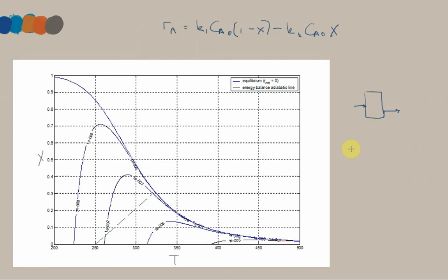So if we look at our general CSTR mass balance, we can normally write FA in times X equals RA V. If we want to achieve a certain X, or as high a conversion as possible, then the fact that as we are progressing here the reaction rate is going down means that for small changes in X, we require a much greater volume, because the reaction rate is so low.